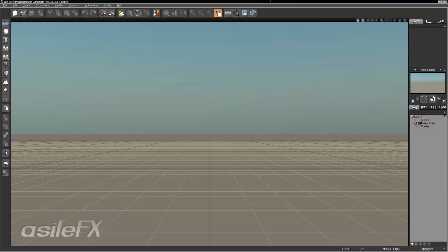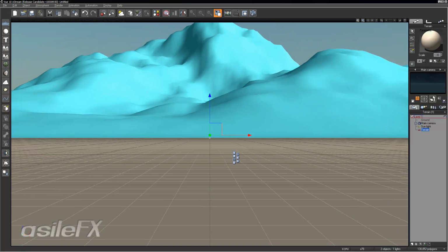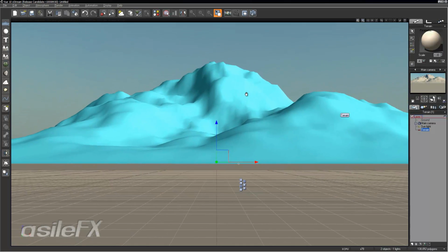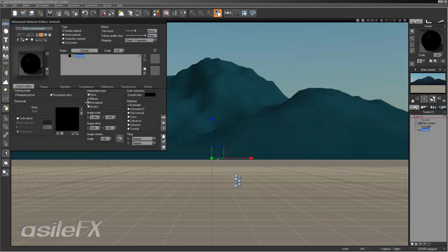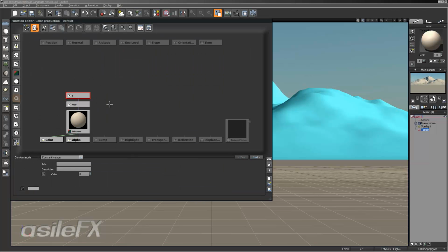I'm now going to be showing you how to set up the camera projection texture map node in case you're unaware of how to do that. I'm just going to add just a standard terrain to the scene, and we're going to edit the material, and we can go to a map picture to start with if you want to load it in and then modify it. For now, I'm going to set it to the procedural colors and set it up manually, because we're going to have to set it up manually anyway.